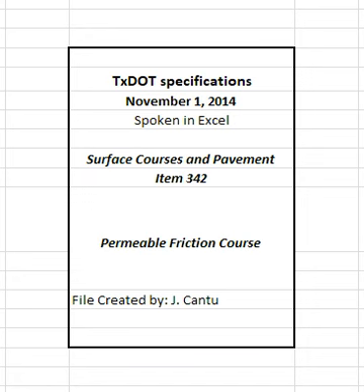Department-owned RAP stockpiles are available for the contractor's use when the stockpile locations are shown on the plans. If department-owned RAP is available for the contractor's use, the contractor may use contractor-owned fractionated RAP and replace it with an equal quantity of department-owned RAP. Unfractionated RAP is not allowed in PFC mixtures. Department-owned RAP generated through required work on the contract is available for the contractor's use when shown on the plans.